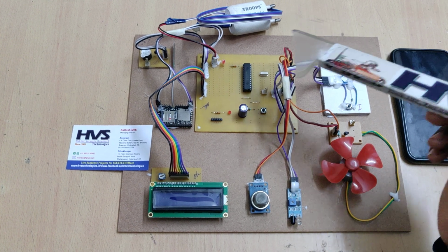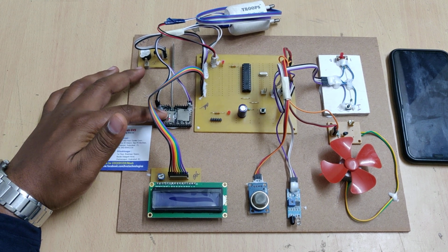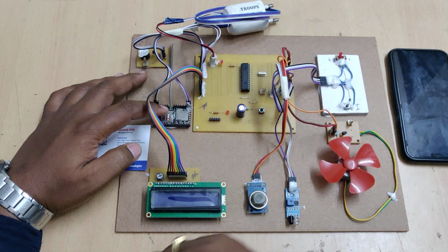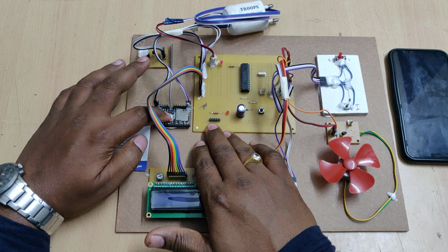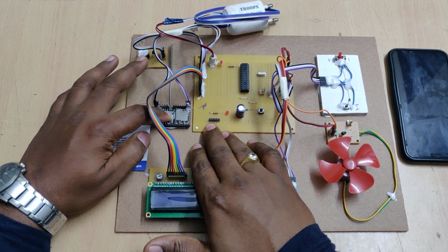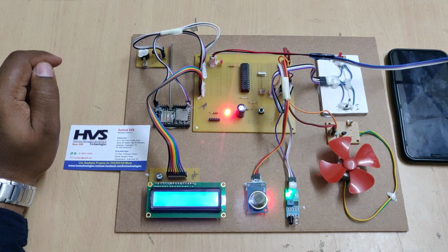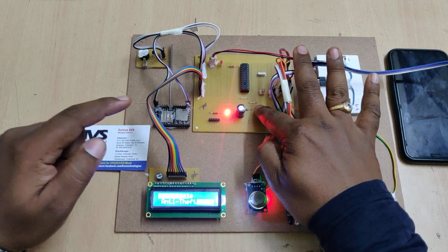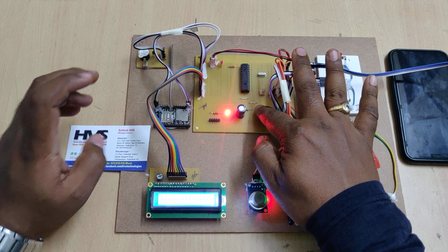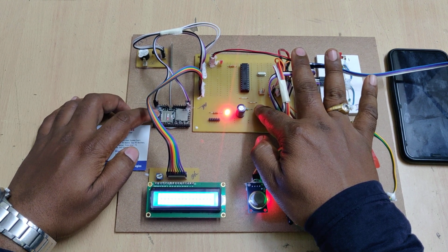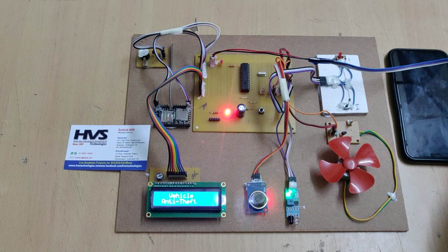Before turning on the kit, we need to insert a valid SIM card. Other than Jio, it is better to use an Airtel SIM card. Insert that valid SIM card by pushing back to unlock, and place it in the proper manner. It is better to use a SIM adapter, then push forward to lock it, and then give the power supply to the adapter. There is a reset switch, so hold the reset switch for around 10 to 15 seconds. In the meantime, it will get the signal from the SIM card we have inserted into the GSM modem. After 10 seconds, you can release the switch so that the controller will start.